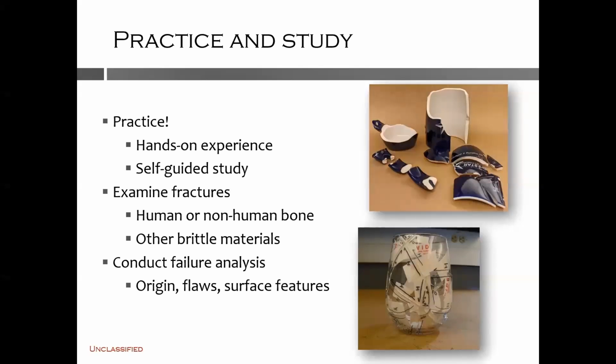So the next time you encounter some sort of fractured material, conduct your own failure analysis. See if you can find the flaws, locate the fracture origin, and determine the direction of crack propagation.